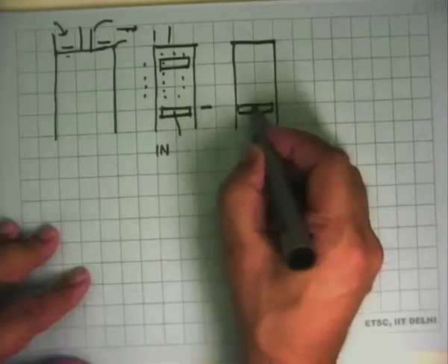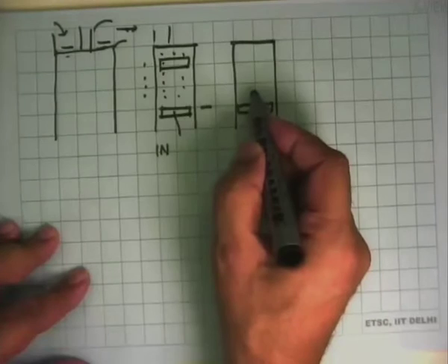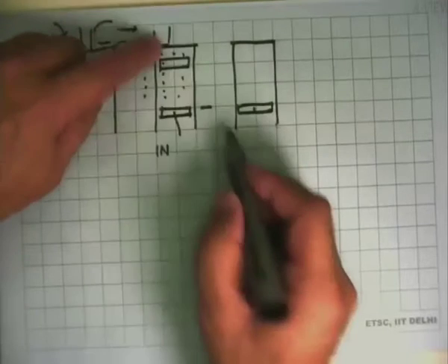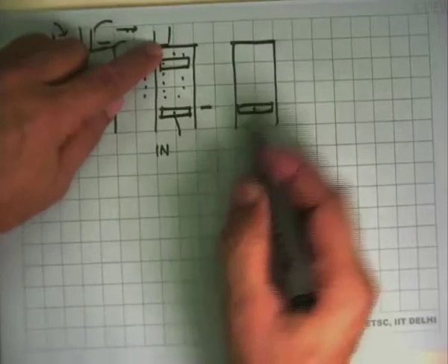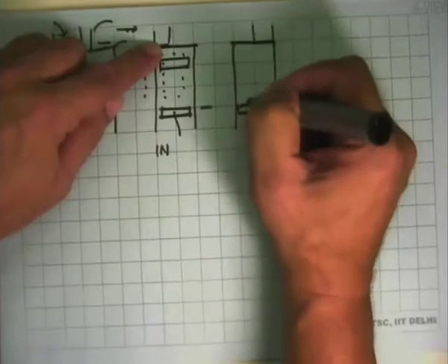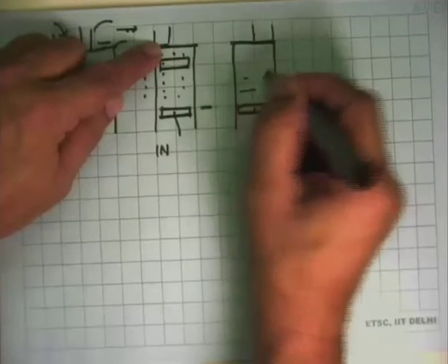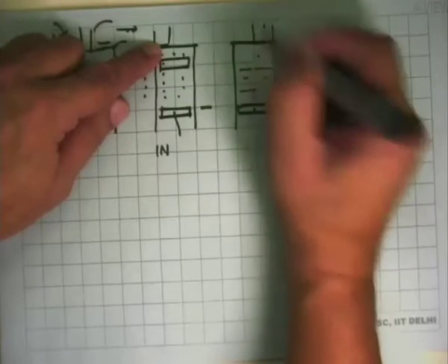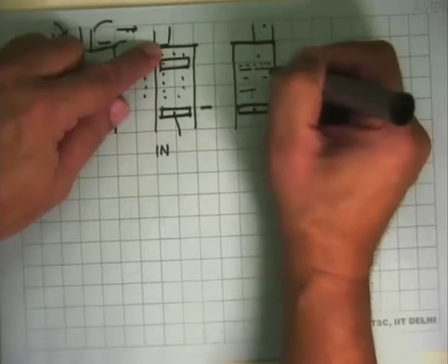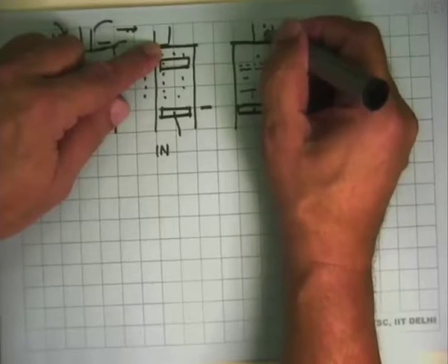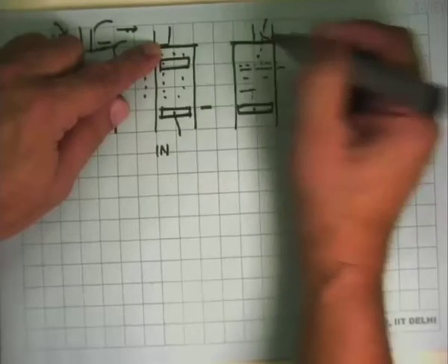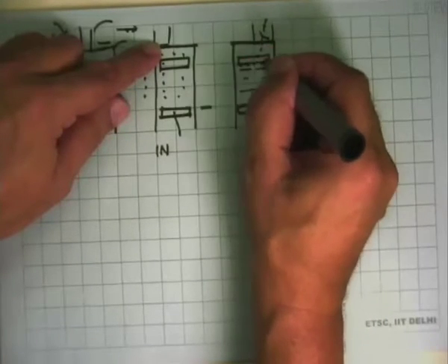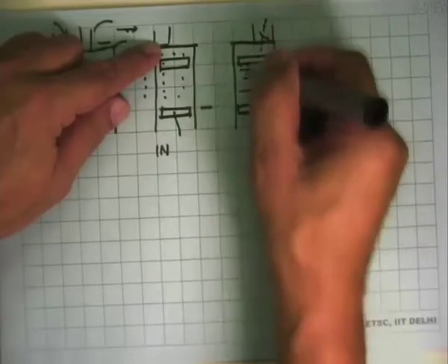The electric motor is driving this. The moment it starts moving up, the pressure inside here becomes more than the pressure here. So this valve will now remain shut. And we'll have to now see what the outlet valve does. So this begins to move up, and as it moves up, the pressure keeps increasing. And at some point, this pressure is equal to the pressure here, and after a slight movement up, the pressure here would be more than this pressure, in which case this valve will open and some of this vapor will be pushed out. It will keep doing it until it reaches its topmost position. So from here to here, it is an open system where it pushed it out.